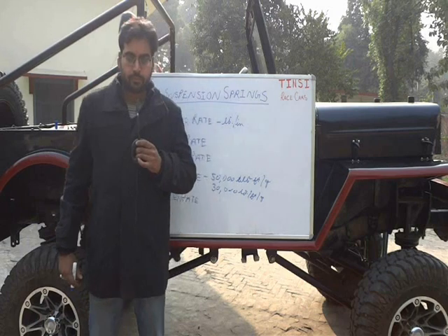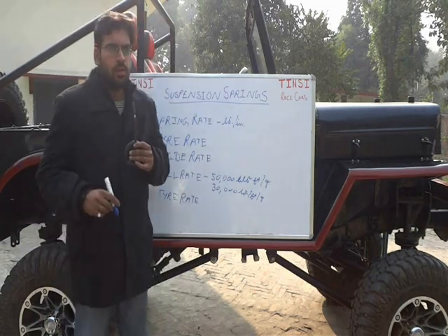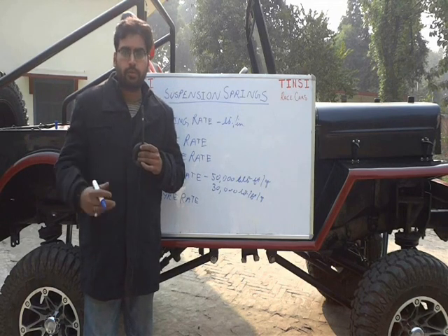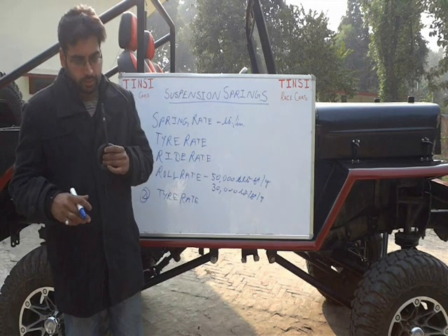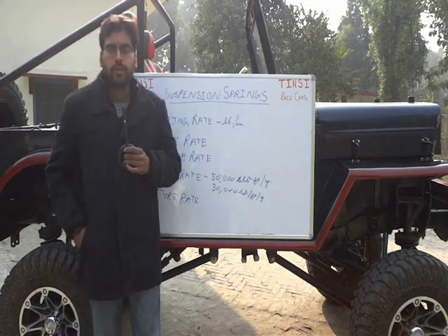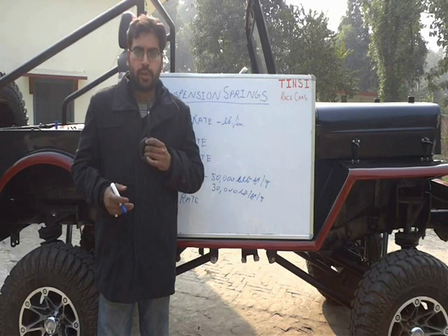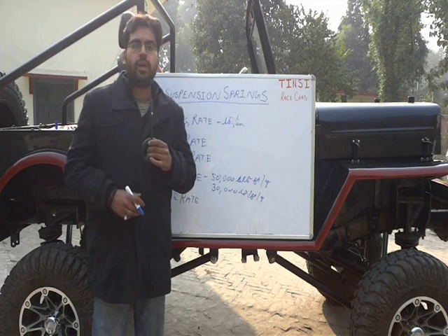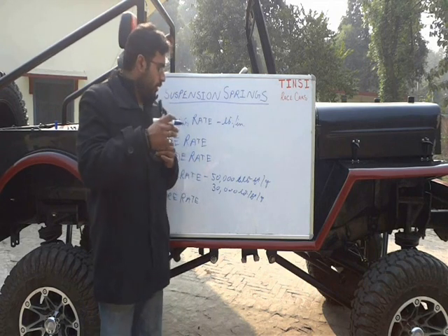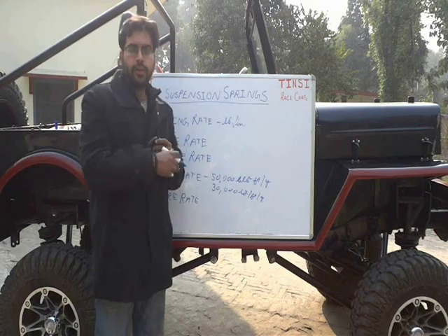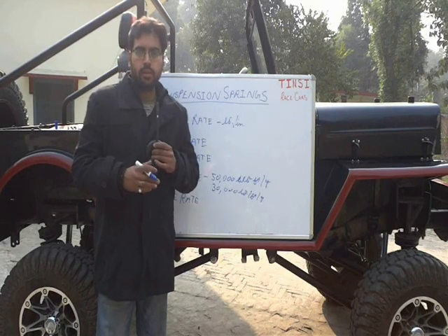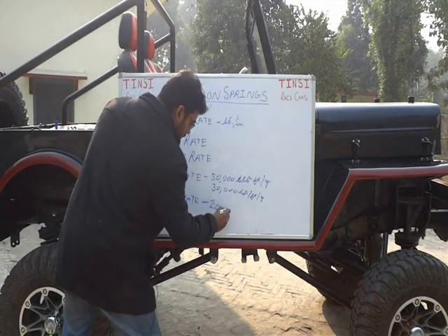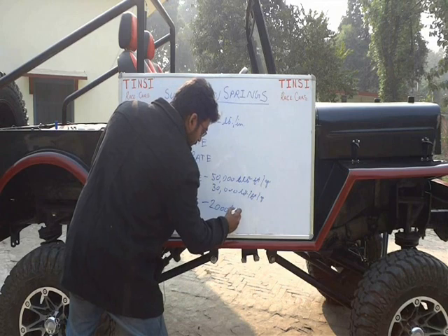Now some of the books will say that you assume a tyre rate. It is generally, for slick tires, around 2000 pounds per inch. But what I'll suggest is, we are also dealers of A1 tires and Cooper tires from UK. So this particular value is given to you in the tire data. Take it from there, for a particular load range and camber and everything, this value is given. Go for the rear values and then proceed. So I'll take this as around 2000 pounds per inch.